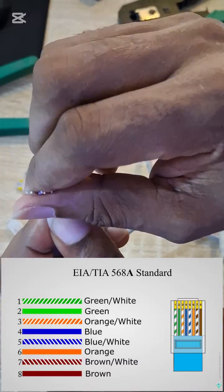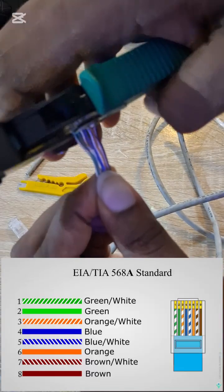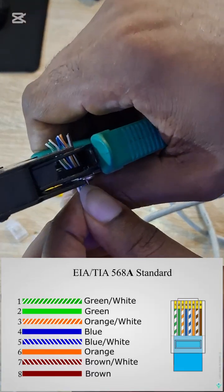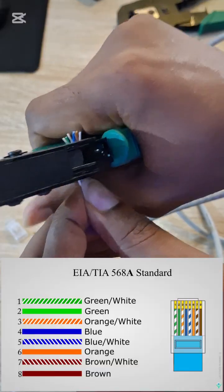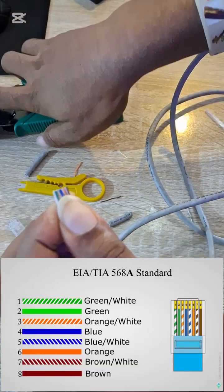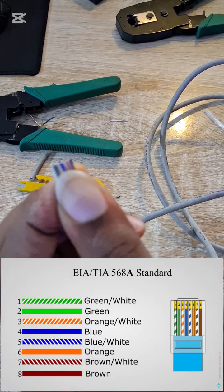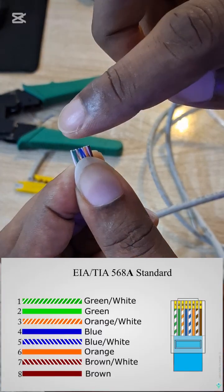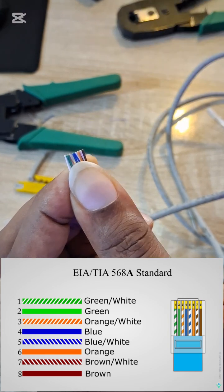So arrange it very well, then cut it to a particular size. So we have white-green, green, white-orange, blue, white-blue, orange, white-brown, brown.